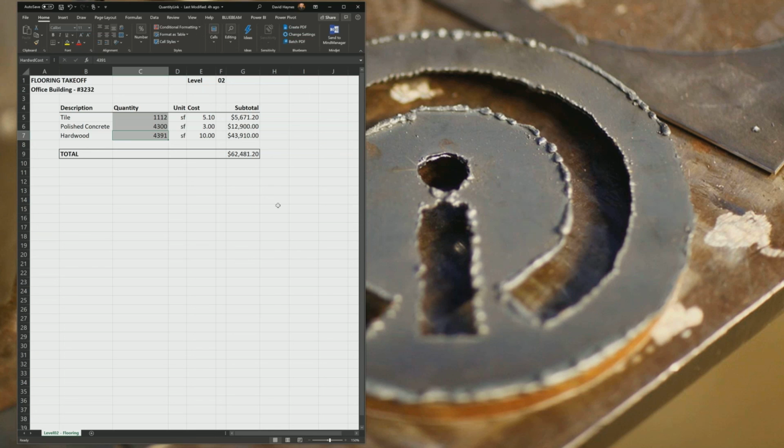And then let's see, does Revu 2016 have the ability to calculate wall area? Yep, it should. Kind of the same way as David had pointed out with the poly length, you should also be able to get the wall area with the 2016 version. The markups for those have remained unchanged, so that's good.